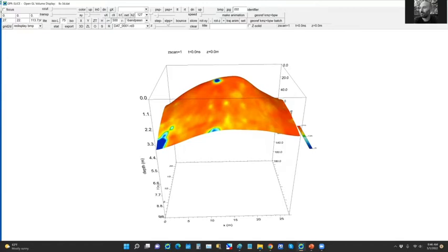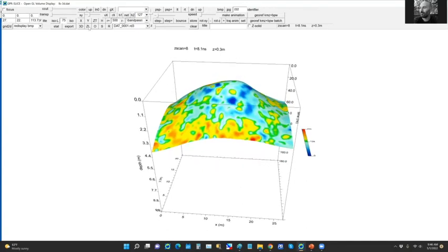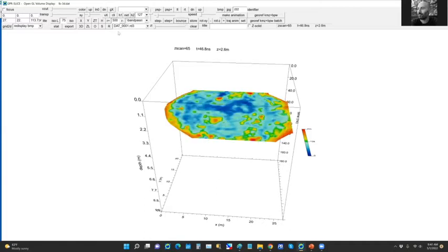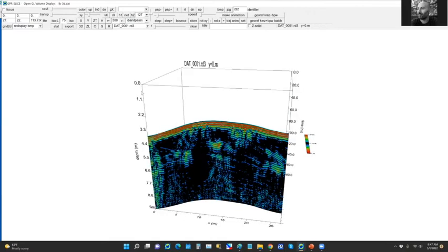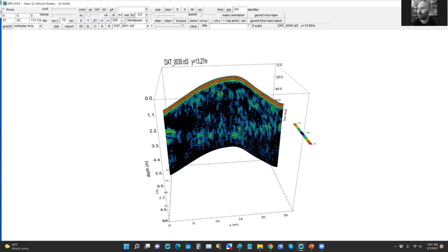If you hit the step minus button, you get what we call ZT, or topographic slices. There's also an option to hit what's called ZL, which are real-time horizontal plane layer slices. So these are plane layer slices, which are real-time and cutting through this warped volume. You can also click on your radargrams, and all the radargrams will be real-time warped into topography.